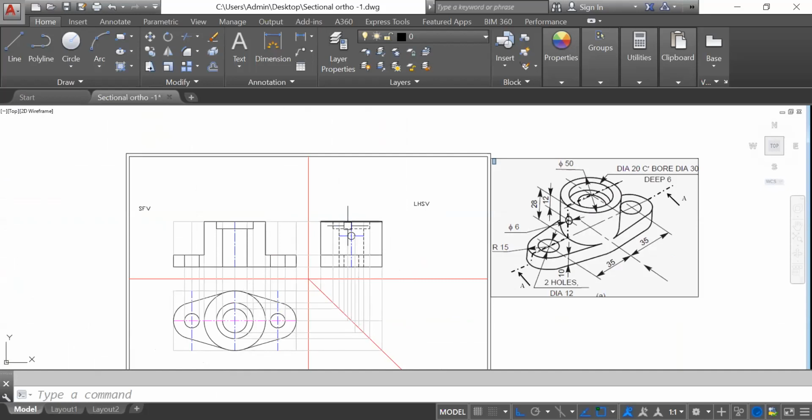So this hole is here, this one is the hole for the side view. Then this hole is for the inside hole, 20 mm dia. Now this hidden part, this hidden line and this hidden line, is for this hole. This hole is hidden in the side view, so that's why it is shown by a hidden line up to only 10 mm thickness, not throughout.